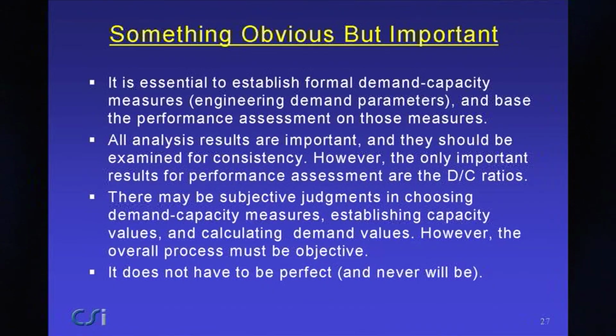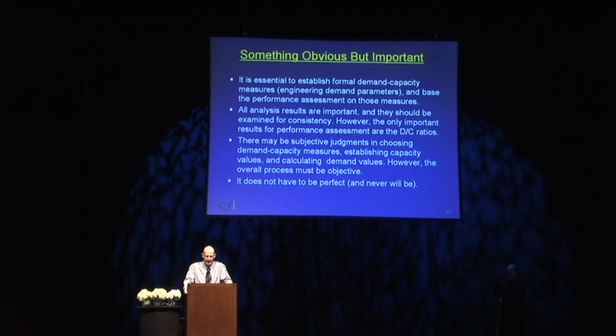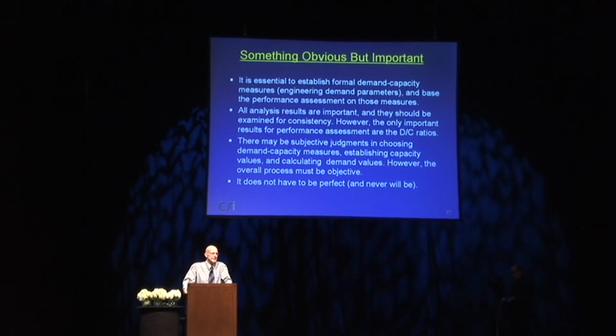This is sort of a philosophical point. It's rather obvious, but it is important. It's essential to establish formal demand capacity measures or engineering demand parameters, and to base a performance assessment on those measures. If you do a nonlinear analysis, you get lots and lots of analysis results. And they're all important, and they certainly should be examined to make sure that your model and your analysis seem to be consistent. But for making a performance assessment, a judgment, the important results are the demand capacity ratios, really nothing else matters. Is demand greater than capacity or is it not?